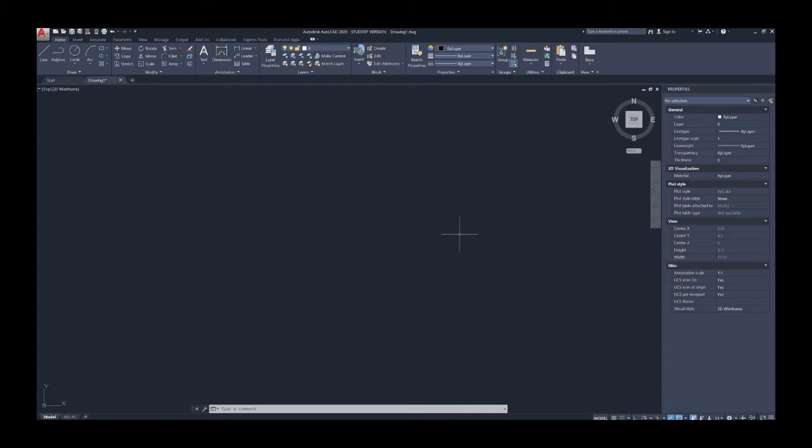So I like to have grid lines on my drawing space. So if you go over to the bottom right of your screen, you'll see that we are in fact in model space. The next tab over is to display a drawing grid, and I really like the drawing grid, so I'm going to put that on. So you can see that it just has this really faint grid line in the background here.